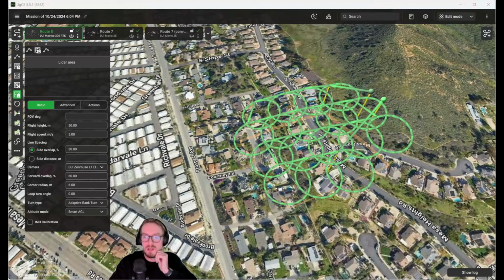From Ryan: is the Circlegrammetry designed to complement linear and grid flight path missions, or is it intended to completely replace them? I'd say it can be a bit of both. In some cases, if you want to do oblique mapping, I believe Circlegrammetry can replace to some extent the double grid oblique missions. But at the same time, if you use a Circlegrammetry mission and then complement that with the standard grid where you just capture nadir images, I think this could also work quite well.